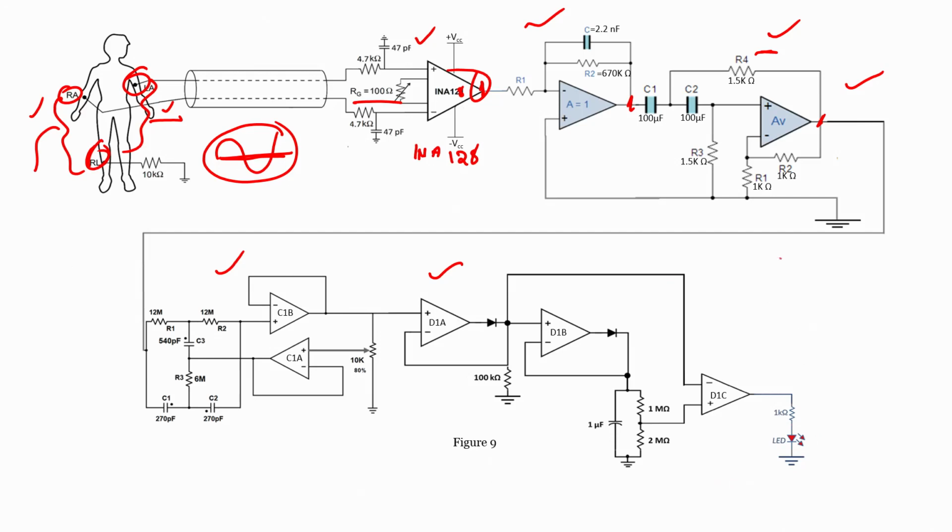Since we are using a DSO, a digital signal oscilloscope, whatever signals we acquire are stored in terms of digital outputs. Even by using our DSO at this particular point, we can easily analyze the BPM of the subject that we are connecting to the input of our amplifier.